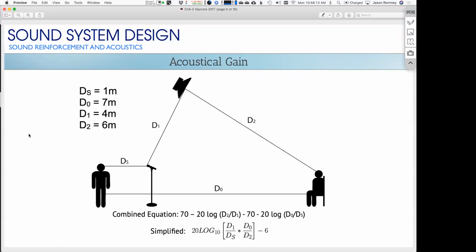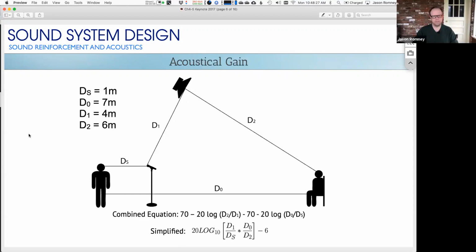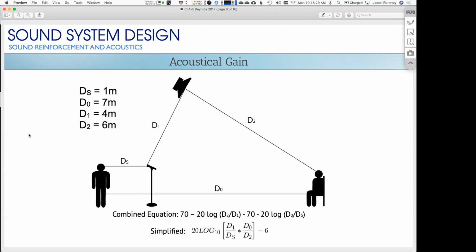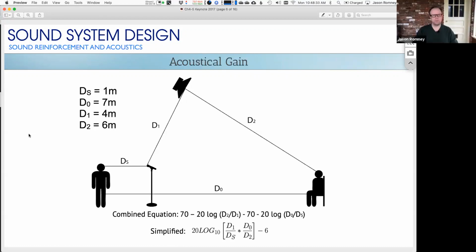Okay, this may be a bigger question, but this summer I worked with a designer that had me take all of the mics and we walked around stage in a silent room, and he had the A1 crank it up until it had feedback, and then he was doing EQ changes. Was that attempting to EQ out gain? Do you know what he was doing? Yeah, this is a process called ringing out the mic or ringing out the system.